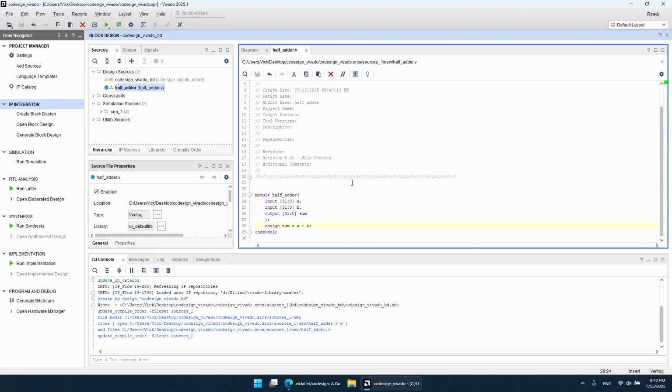So the output of this 32-bit half adder will then be used to turn on a set of LEDs on the board, and as a return value to the program we'll develop in subsequent videos. As you can see here, the sum, which is our output, has 32 bits, but our AUP ZU3 board has 8 LEDs. So we'll be lighting up these 8 and ignoring the remaining subset. Let's return to the block designer.